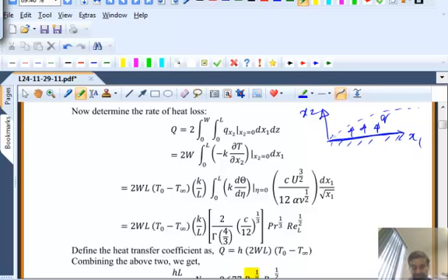In heat transfer, as we saw in flow inside a pipe, there are two situations that one can normally encounter. In fluid mechanics, typically at a solid boundary, you have zero velocities. Okay? But in heat transfer, you can maintain this surface at a constant temperature, which is what we did right now, or you can maintain it at a constant flux. Both are physically realizable. How would you maintain a surface at a constant temperature?